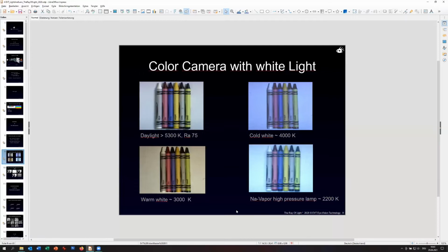You can test this. It's really amazing, and only if you saw it, you will see the effect of these different light colors. This is one of the reasons why most of the machine vision is done with gray cameras today, not because of the bigger amount of color images. It's more the stability at the end. And of course, also for gray images, it's important to have a stable light, but they are not influenced so hardly by the color change of the light.